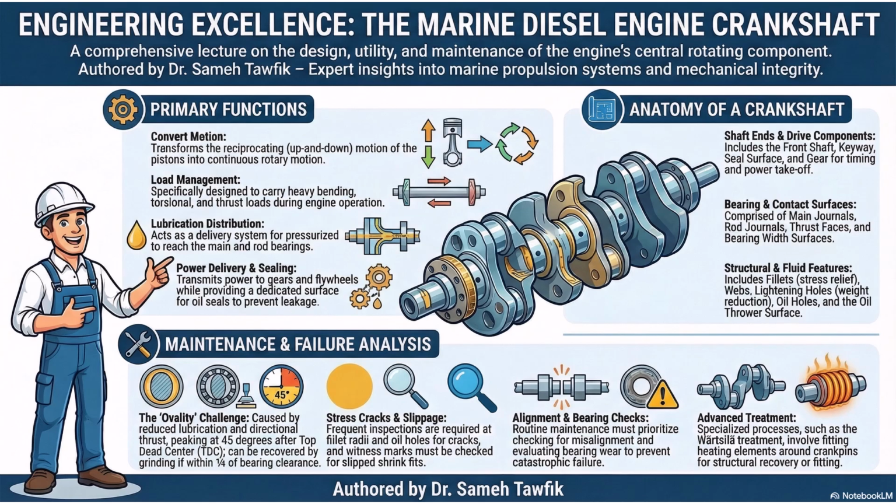We also have to look closely at the surfaces engineered specifically for managing friction, fluid retention, lateral movement. The diagram points those out too? Yeah, it points out the seal surface on the end, which is critical for oil retention. And the thrust faces machined onto the sides of the webs. Those are super important. Vital. Because a crankshaft isn't just dealing with rotational and downward force, it's dealing with longitudinal movement, sideways forces that literally try to push the shaft right out of the block.